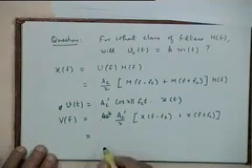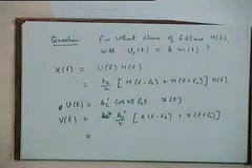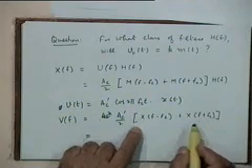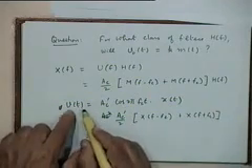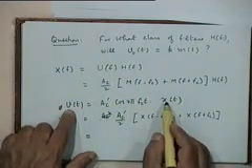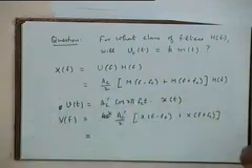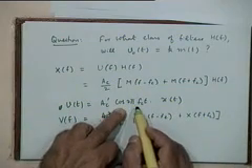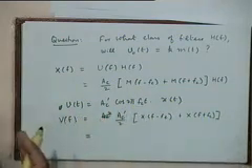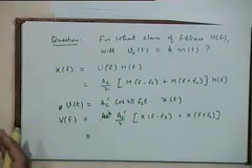So now out of these 4 terms, can I identify the 2 terms first which will be in the baseband, because this is a band pass signal, isn't it? This X of F is a band pass signal. That's a modulated signal. When you are doing frequency translation of that, you will get a component translated around the 0 frequency and a component translated around twice the carrier frequency. So can we identify these 2 parts separately?